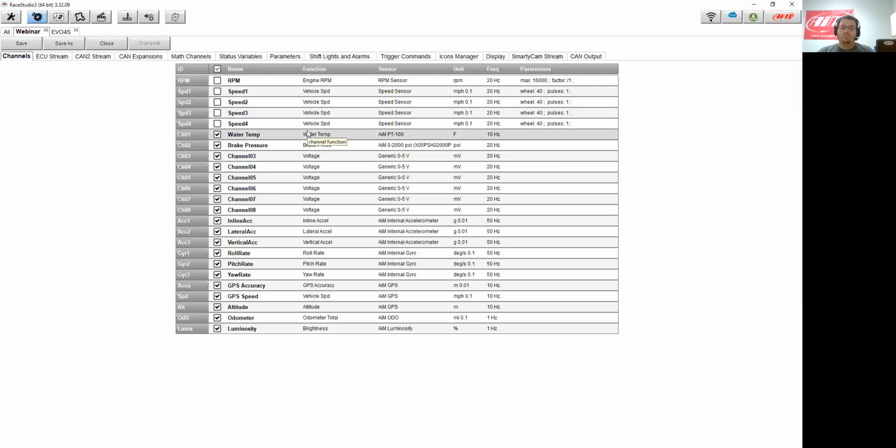And when you connect a sensor, you'll need to set it up here. At the top, you have RPM. This is our analog RPM. This is simply the physical RPM connection looking for a square wave signal. This is not your engine RPM from the ECU, which sometimes does get confused.